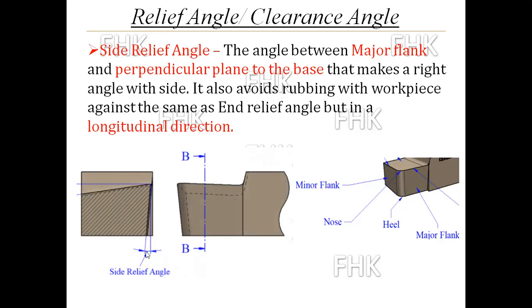The angle made by the major flank and the plane perpendicular to the base is called the side relief angle, and it also avoids rubbing of the workpiece against the tool, the same as the end relief angle, but in the longitudinal direction.